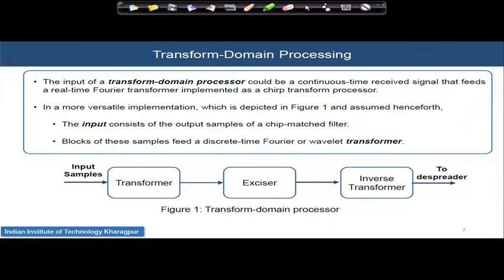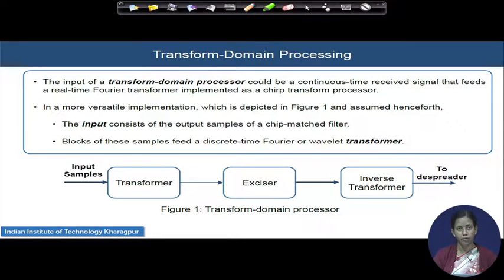The exciser can also be implemented by an adaptive filter architecture, if you feel that the interference is static in nature. At that time the adaptive algorithm selects non-binary weights for the output of each and every beam, and the algorithm should be designed in such a way that the weighted output and the desired signal's transformed output perfectly match with each other with minimal error.